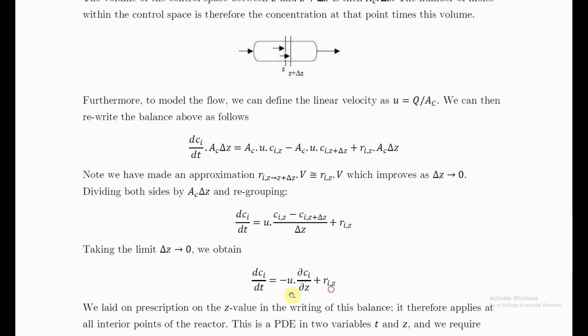You've got the accumulation term, and your two flow terms, flow in and flow out, which for a flat disk actually give us a single derivative. Remember, that's where this came from. If you look up here, the flow in minus flow out actually turns out to be a gradient across this disk. So that's there, and then the reaction term.